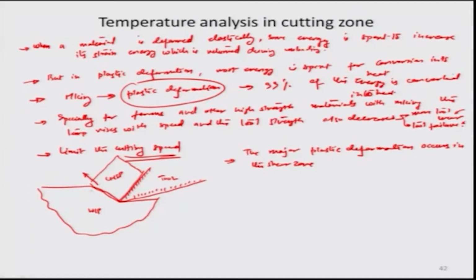So, when this chip is shearing off with respect to the workpiece, this is plastic deformation mostly converted into heat, and so there would be heat coming out in both these directions from this primary shear zone. This is because of the nature of the plastic deformation process here, which is really the determinant of the material removal. This is a heat source